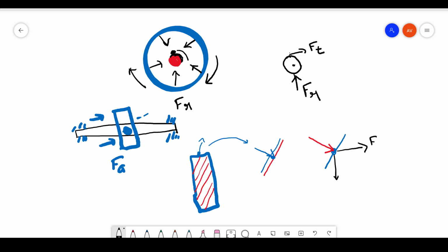You can see this is your axial force, because your total gear is going to be like this. This again contributes to your tangential force. So there is an axial force because of this particular engagement with another gear. That is how you get an axial force here.